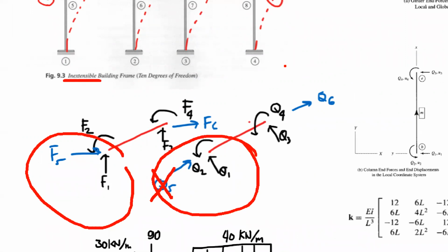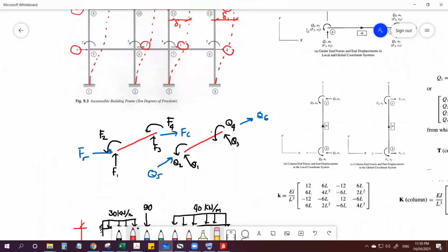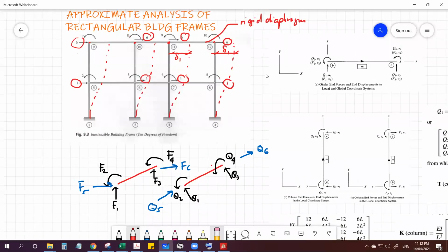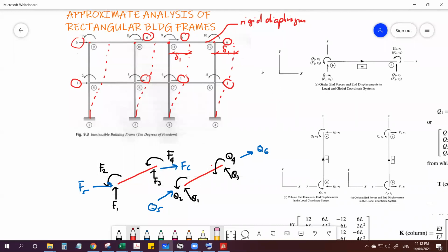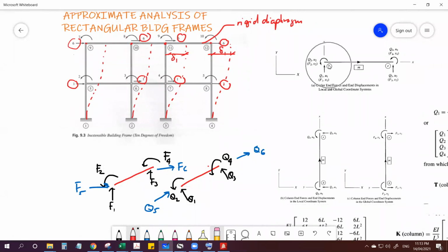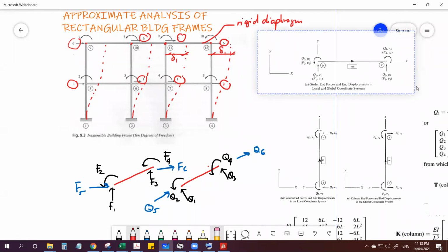On a typical concrete structure, let's say a low-rise building, axial deformation is really not that much. Okay, so that assumption again reduces the required stiffness matrix. So no axial deformation like in our original beam stiffness matrix, and just rotation. Right?